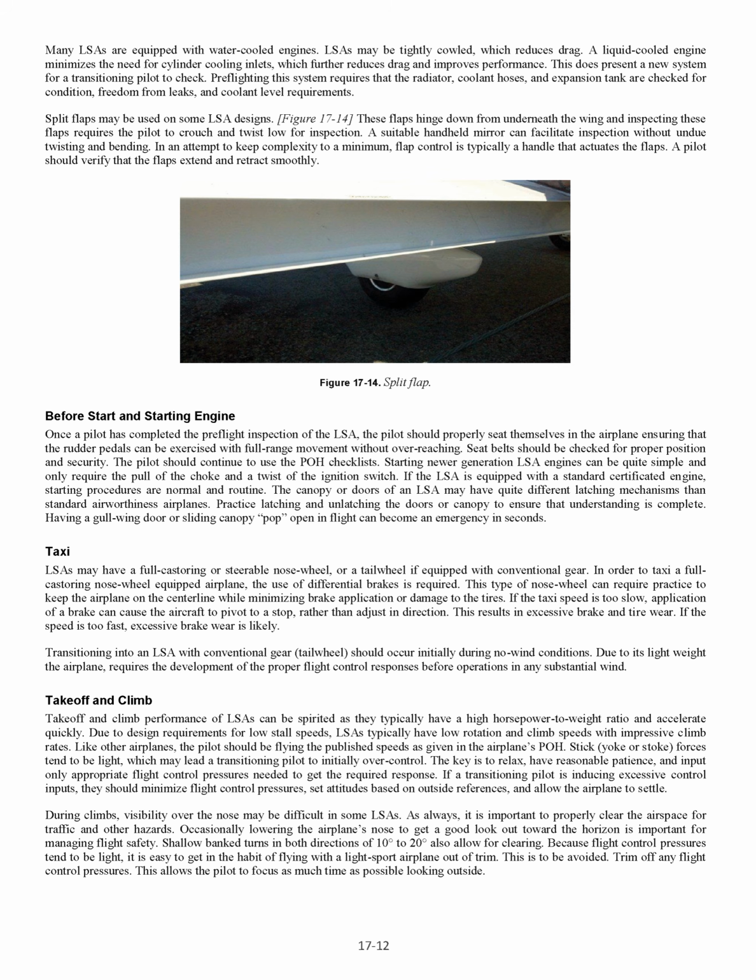Transitioning into an LSA with conventional gear, tail wheel, should occur initially during no wind conditions. Due to its light weight, the airplane requires the development of the proper flight control responses before operations in any substantial wind.